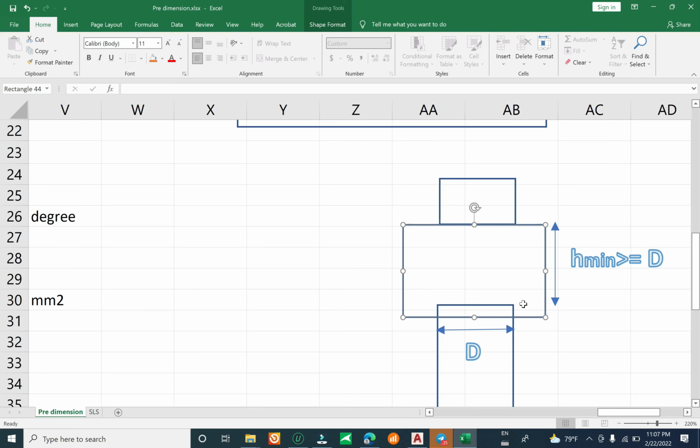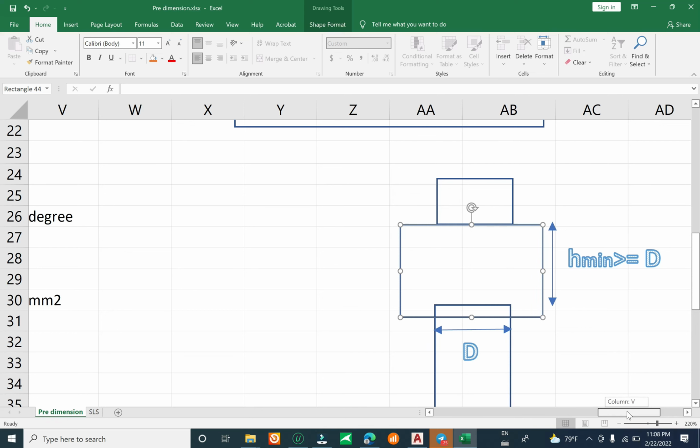If you take this height greater than the diameter of the bored pile or of the driven pile, then you use the minimum bar reinforcement in this section, which is enough for the pile with the load applied at the center of gravity. Okay, not eccentric. In the case of eccentricity you have to add a beam or add an element to reduce that eccentricity.